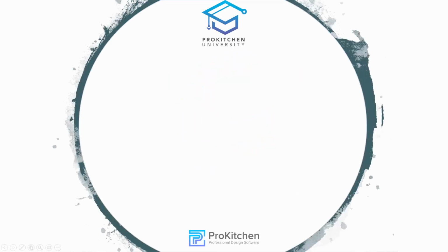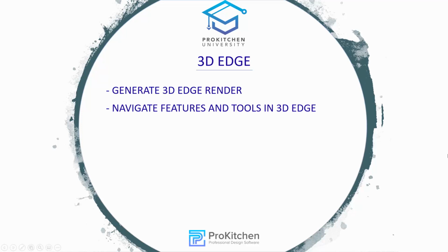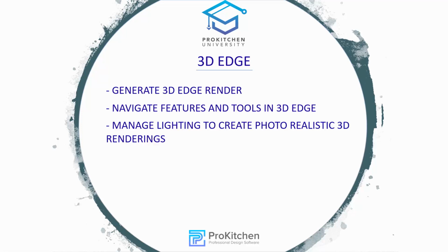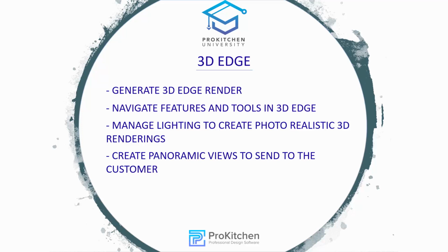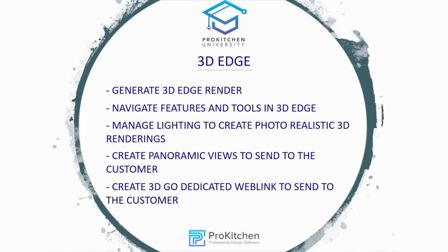In this video, we will be exploring 3D Edge. We will generate a 3D Edge render, navigate features and tools in 3D Edge, manage lighting to create photorealistic 3D renderings, create panoramic views to send to the customer, and create a 3D Go dedicated web link to send to the customer.